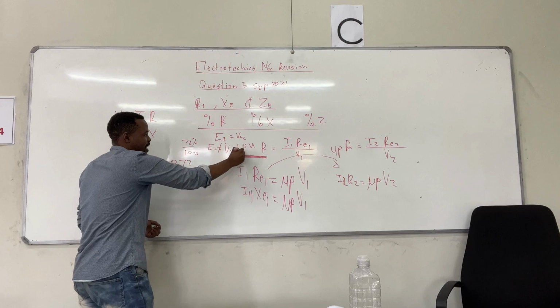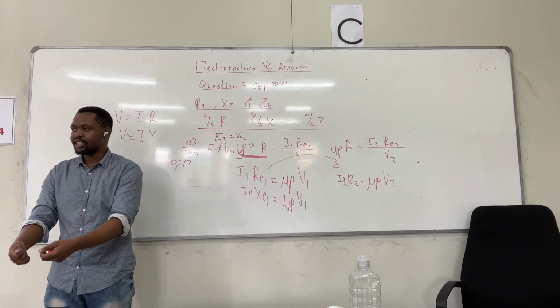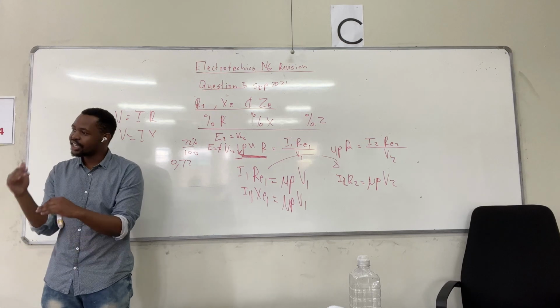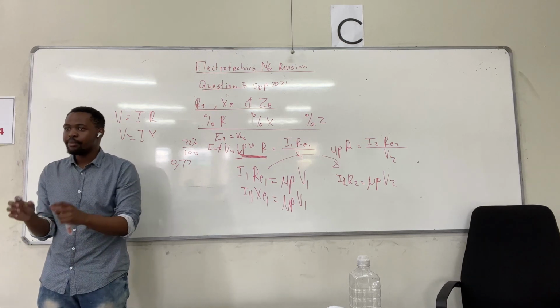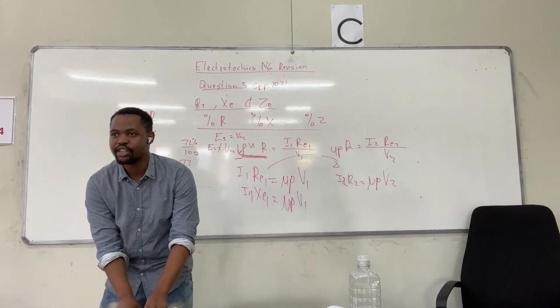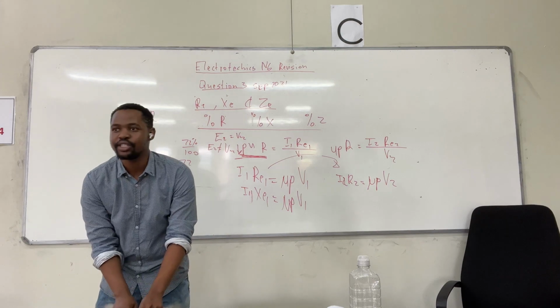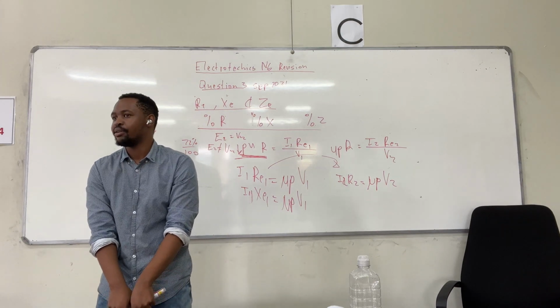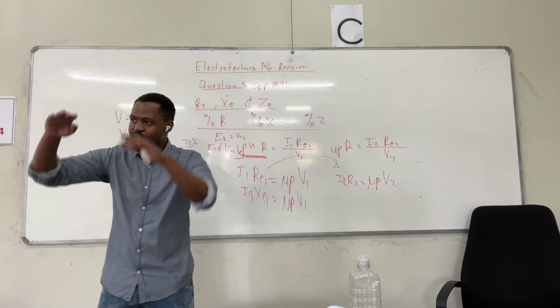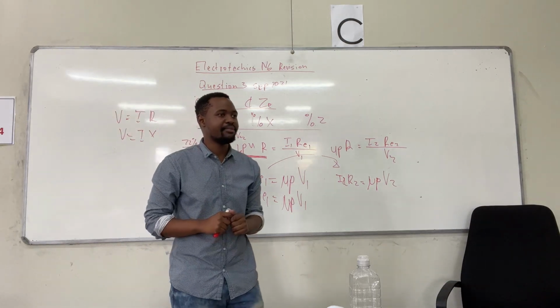So it was less. It's like a battery. A battery can measure open circuit voltage, and you get a higher voltage. But once you connect the battery into a circuit where current is now flowing, you start having internal voltage drop in that battery. Hence the external voltage is now slightly low because you have connected something.